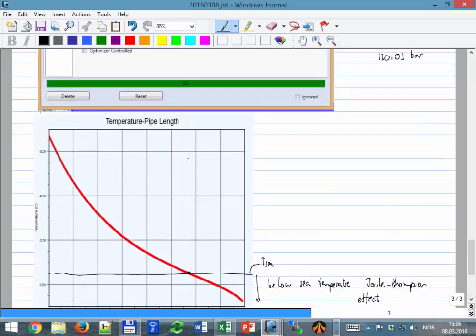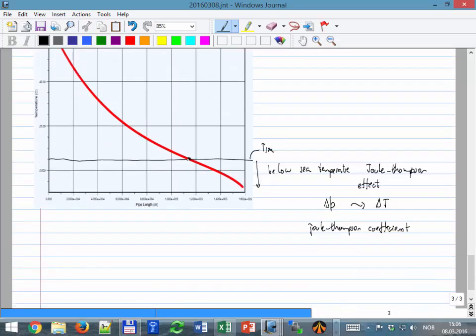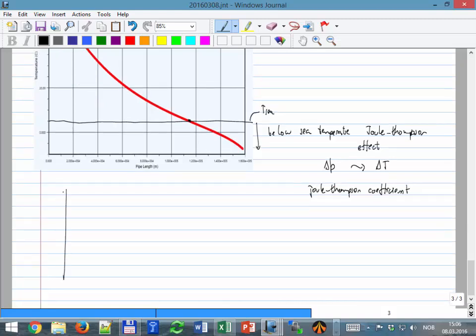Now, we are almost finished with that. I'm just going to show you, because we want to make one last plot that is the phase envelope, P and T. We want to see how is the evolution of the line in the phase envelope. So I'm going to show you some tricks how to get that value from Hysys, and then we just try to close the flow assurance part. Before we go to the break, any question? No? Okay, let's take a break.